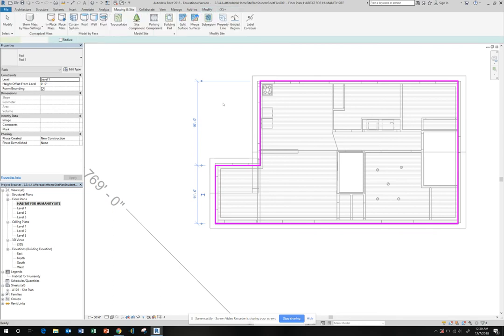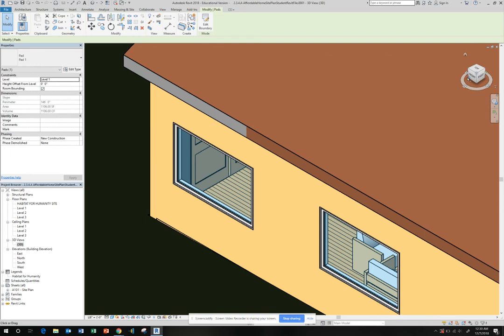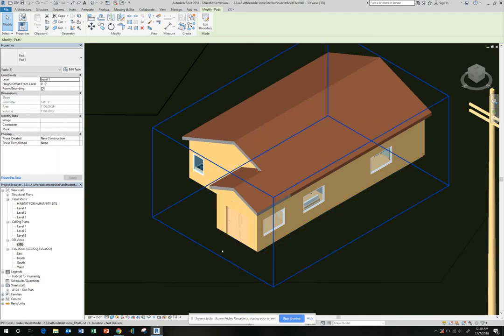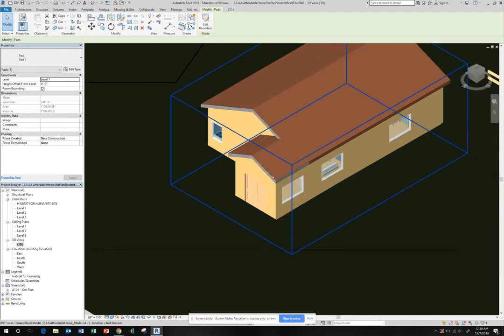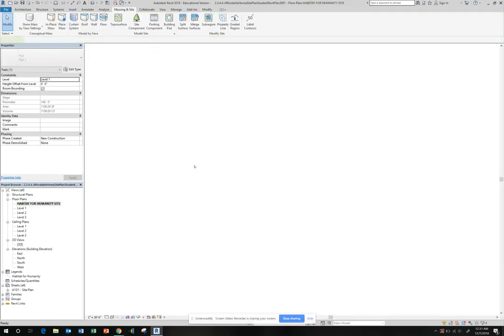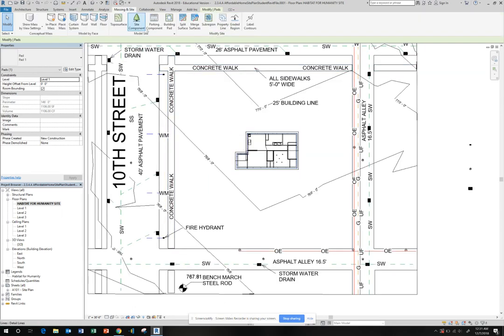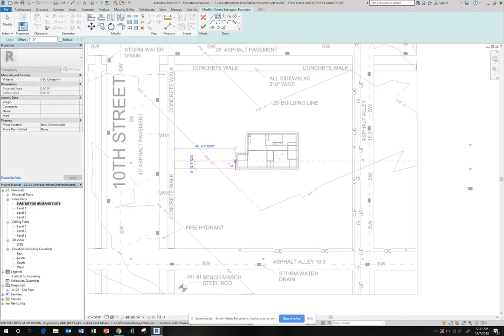Great. So now if I go to the 3D view, you note that it's again hardwood in there. The grass is still there, but there's like a building pad underneath, which this sits on, and the grass is no more. The great part about this is you can go ahead and start creating your sidewalks. So what I would do is go to massing and site, create a subregion. You're going to draw what that looks like. That might be a sidewalk from here to here,